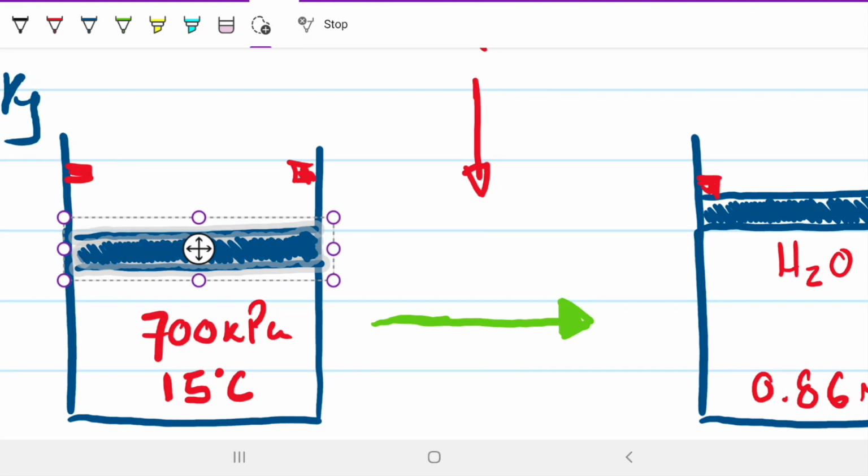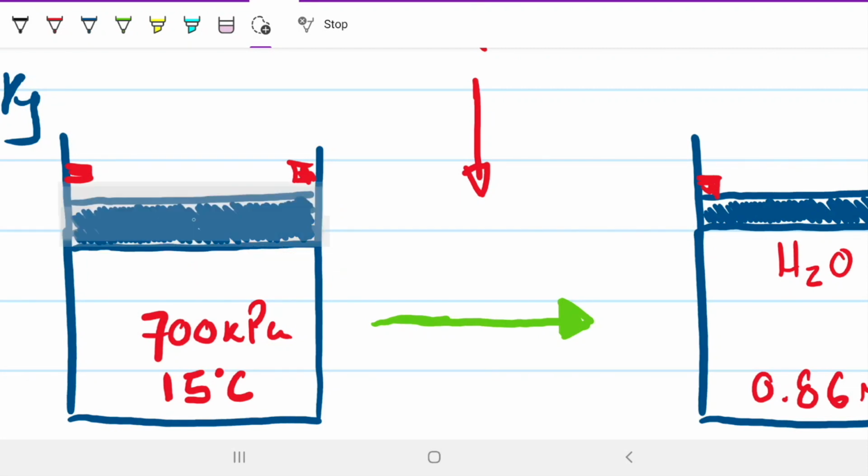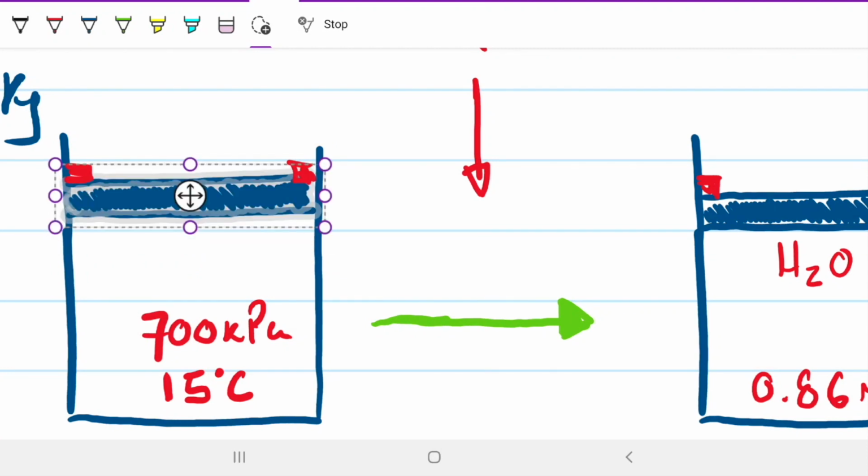And we're back to where we were with the two pressures pushing up and down, but now with a bigger volume. As long as the heat is being added slowly, the same thing is going to happen. More energy is going to come through. The pressure increases until we can push upwards, and then the volume expands a bit. The energy is used in the form of work for it to expand, and the pressure is back to 700. And that's going to keep happening until my piston reaches those stops there, right?